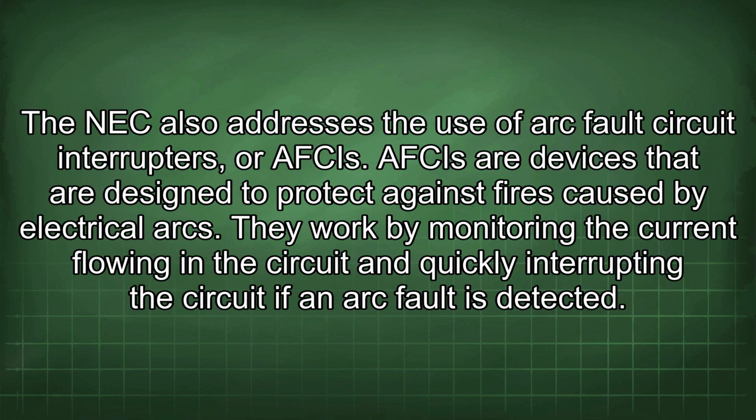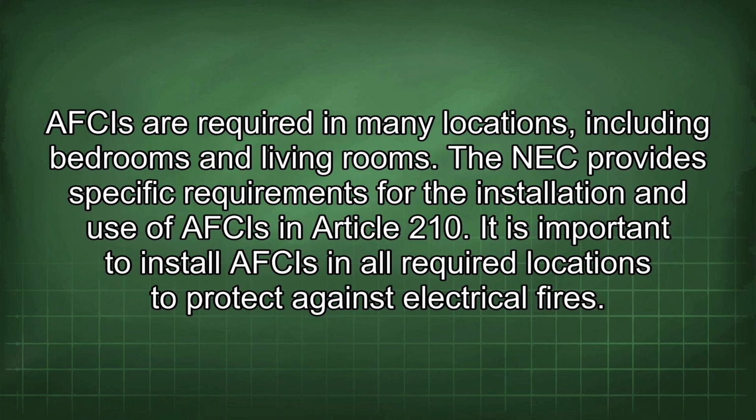The NEC also addresses the use of arc fault circuit interrupters, or AFCIs. AFCIs are devices that are designed to protect against fires caused by electrical arcs. They work by monitoring the current flowing in the circuit and quickly interrupting the circuit if an arc fault is detected. AFCIs are required in many locations, including bedrooms and living rooms. The NEC provides specific requirements for the installation and use of AFCIs in Article 210. It is important to install AFCIs in all required locations to protect against electrical fires.